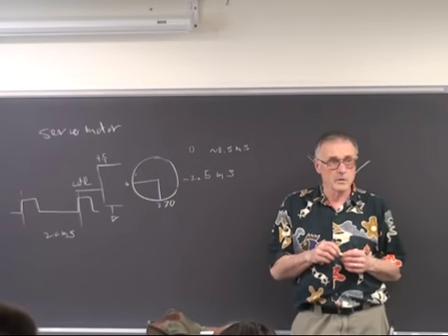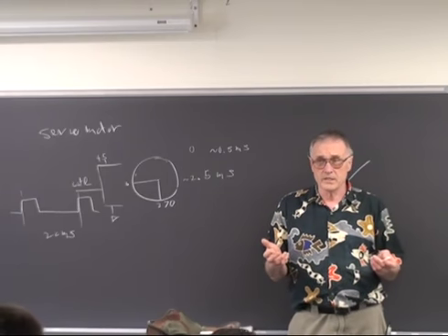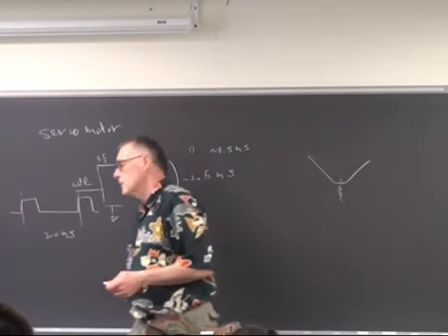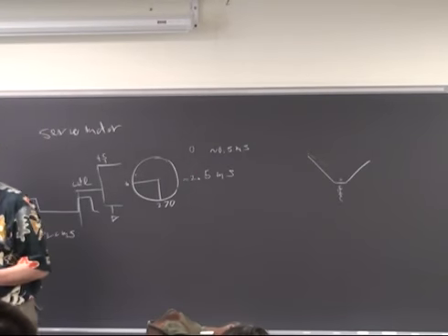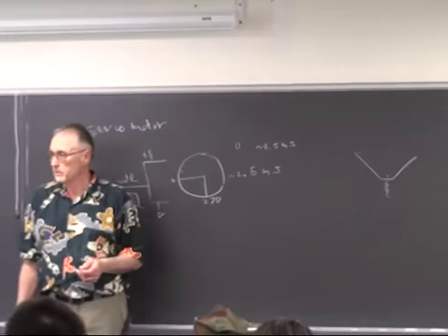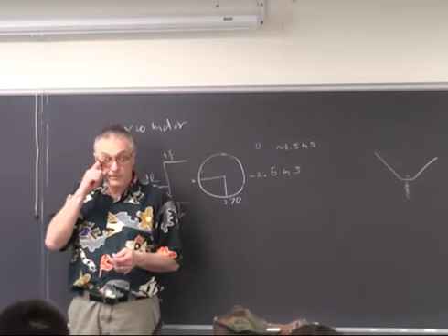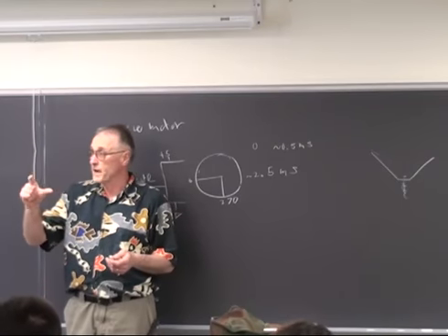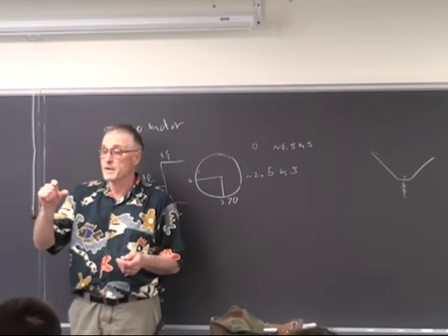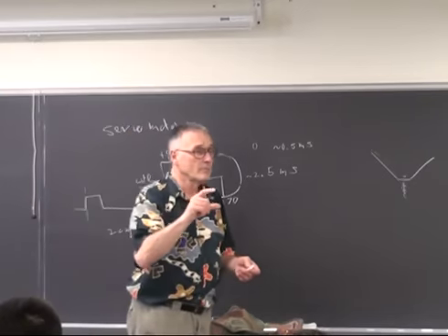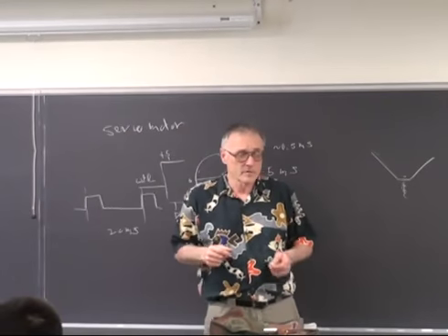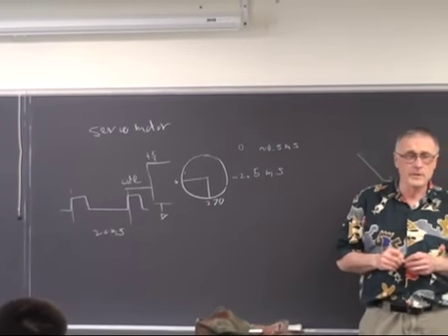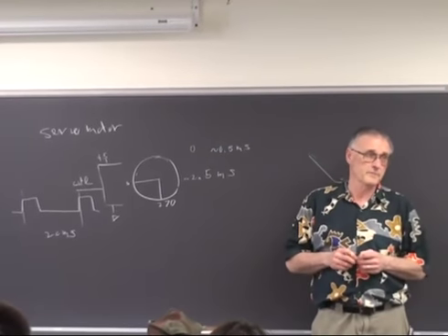Piezoelectric motors? Piezoelectricity is a phenomenon where a piece of material changes size with electric field. If you have a large enough change in size, then you can treat this as a linear actuator or a rotary actuator and move something around, typically a few microns, but sometimes as much as a millimeter, but with phenomenal force.